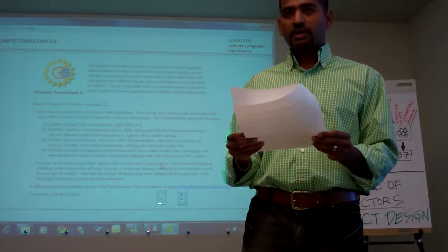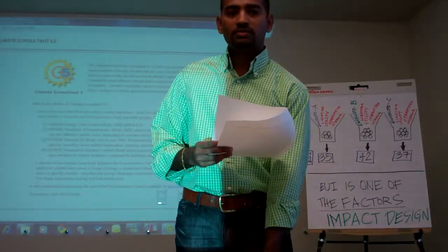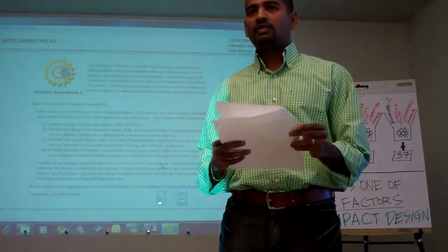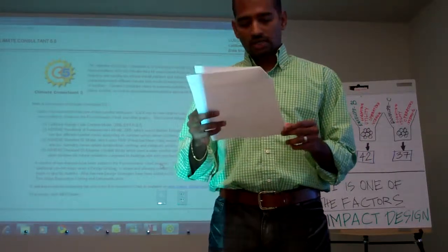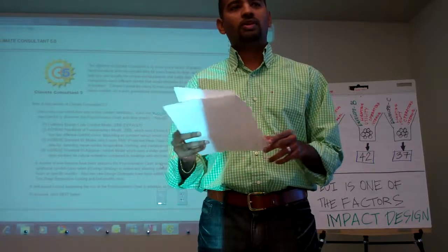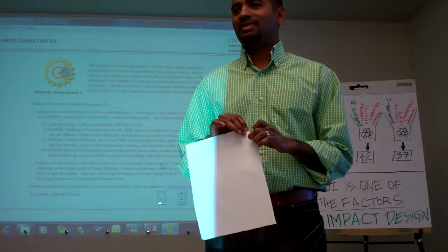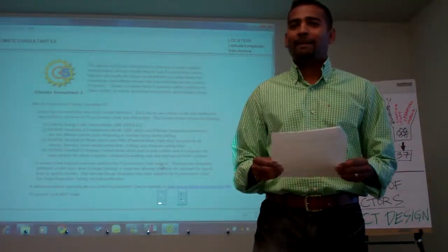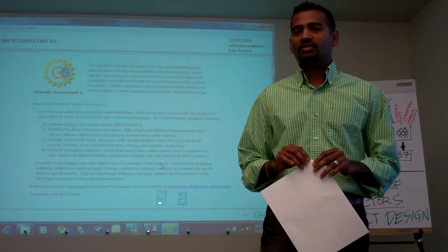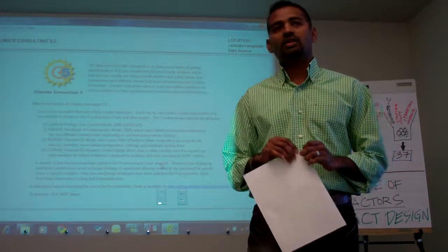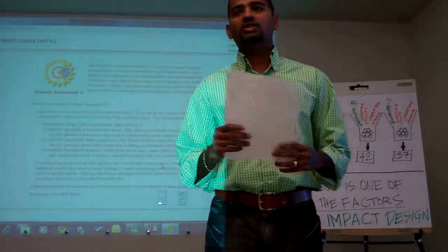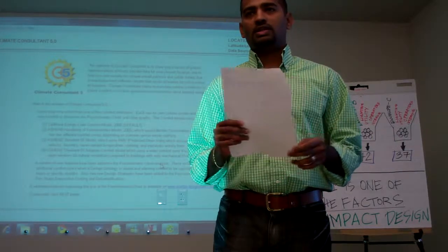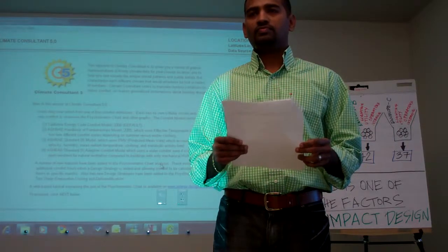Alright, anybody did their homework for last week? Had a chance to think about it? The homework was to find out the average building's EUI for your project, and as a bonus point, to find out your project's EUI. Source energy use, site energy use. Which one do we want? We went through that on week 2. Site. We want the site EUI. So the average building is 76. So our target would be 30.